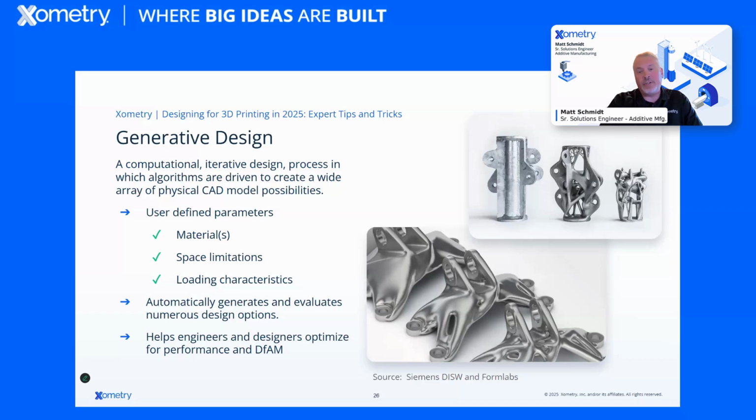You can see some of the topology optimization come in as the iterations go from left to right on that mount. This is only possible in a 3D printing situation. In the upper right-hand corner, we've got an example from Formlabs that shows a welded assembly transformed into an additive manufacturing component that is consolidating those parts, optimizing material usage, and coming out with a really organic design that can only be 3D printed. This is where you're adding value to additive manufacturing and creating huge value.